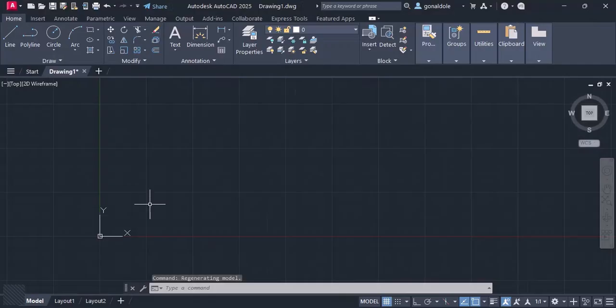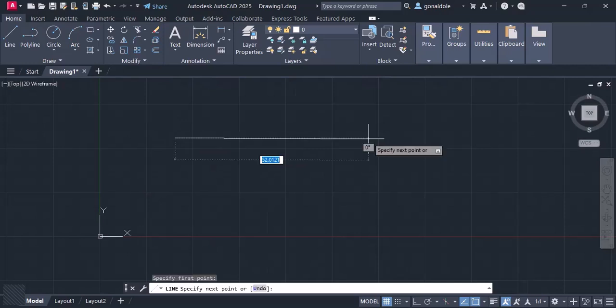How do you draw a simple line on AutoCAD? You left click on the command, then drag the mouse to your screen, and it gives you the option to specify the first point. Then you left click anywhere on the screen. You'll notice my line is not perfectly straight, and I would really have to assume I'm drawing a perfectly straight line, which most times might not be correct.